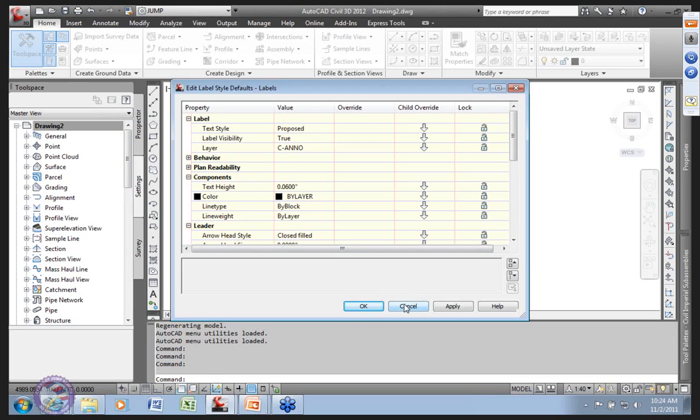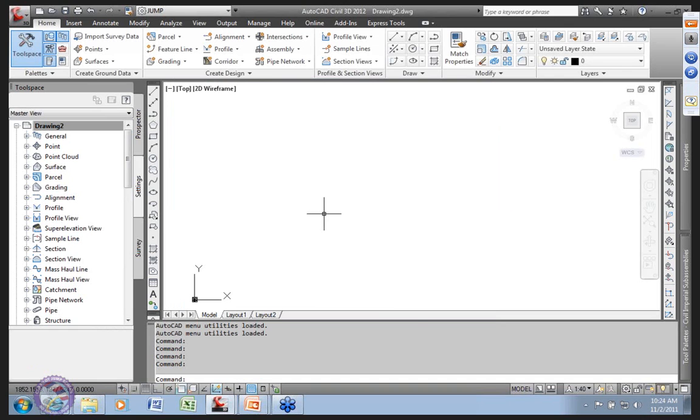If you build good sets of styles and employ this structured approach, then changing your plan to look completely different, to not use Arial, Windows, TrueType, but use old school Simplex or Times New Roman, or whatever your client demands, is a reasonably easy thing to do, because we obey those hierarchy rules inside the jump. And whatever you do, better employ those.